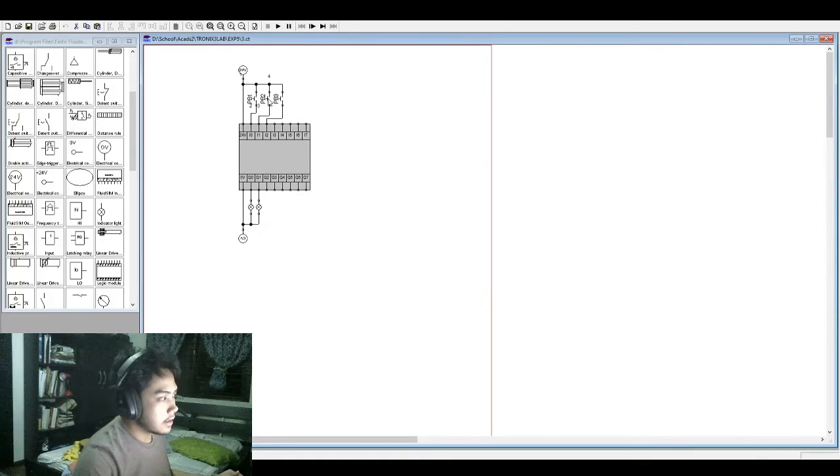And not only should it disable the second push button, but the lamp should also be turned on, or should stay on, even if we release the switch that we pressed, because that is the characteristic of a relay latching circuit. So a relay latching circuit is a circuit that still satisfies the condition even after you release the switch, or even if you change the input.